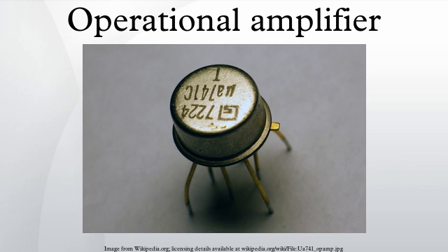This internal compensation is provided to achieve unconditional stability of the amplifier in negative feedback configurations where the feedback network is non-reactive and the closed-loop gain is unity or higher. By contrast, amplifiers requiring external compensation, such as the μA748, may require external compensation or closed-loop gain significantly higher than unity.